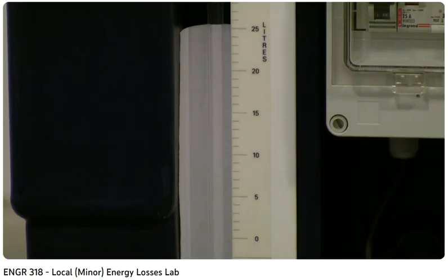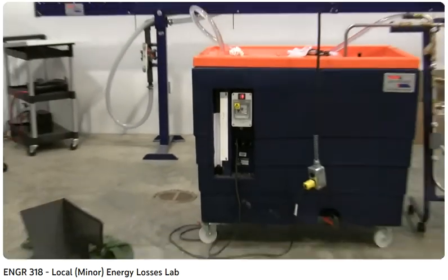All right, so now what you should have done is observed how long it takes to accumulate a certain volume. I'm going to open the plug on the wet well now. We've quantified the flow rate, and since I'm not going to be changing any of the fittings as we take pressure measurements, the flow rate won't change. If I change the position of any kind of valve, then I'd need to re-quantify the flow rate, but that's not going to be happening.